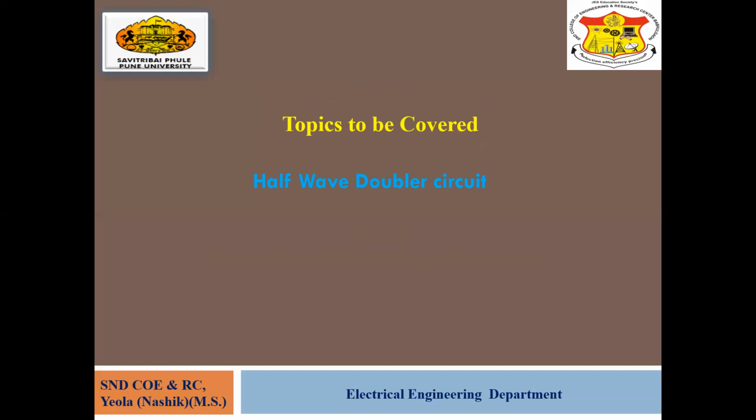Why is it essential to study the doubler circuit? Because when we saw the half wave and full wave rectifier circuits, the DC voltage generated is always less than the AC maximum voltage. But we have to go for the generation of high DC voltage, so for this purpose doubler circuits are used. A doubler circuit means the output is double the supply voltage that is given on the AC side.